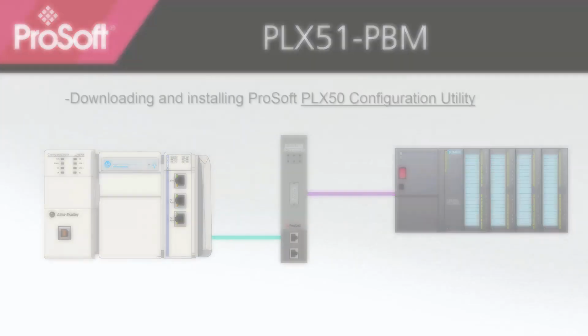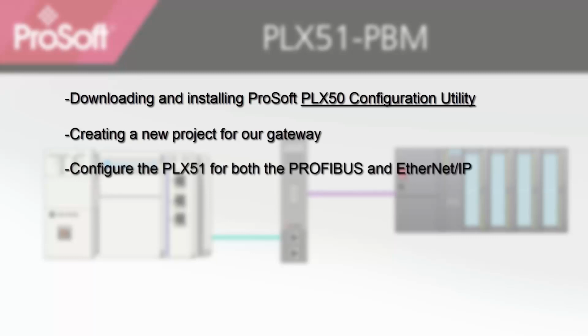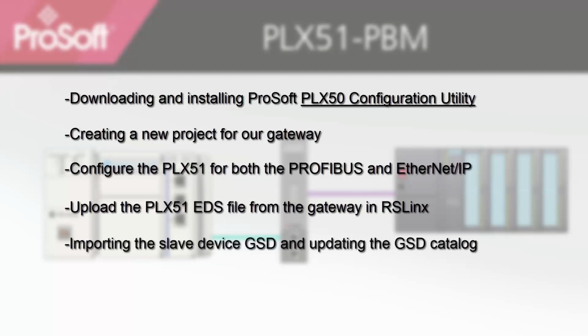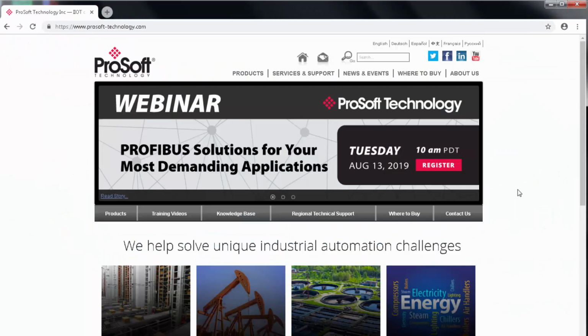So we'll cover downloading and installing the PLX50 configuration utility software, creating a new project for our gateway, configuring the PLX51 for both the PROFIBUS and EIP networks, uploading the PLX51 EDS file from the gateway in RSLinx, importing the slave device GSD file and updating the GSD catalog, and finally we'll look at some features including PROFIBUS DP packet capture.